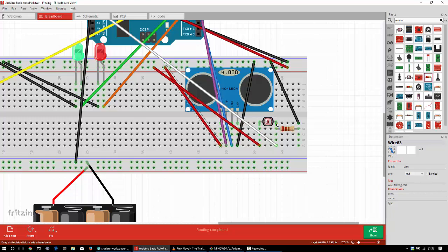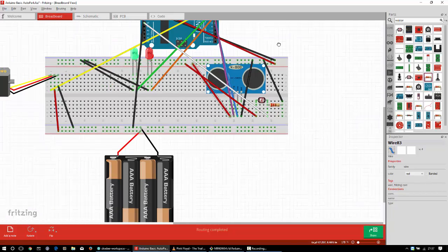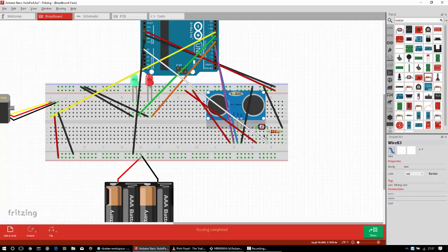In this example, on the right leg you put one resistor, and at the other leg of the resistor you connect the ground. On the other leg of the LDR you connect 5 volts, and on the first leg you connect to the pin as well. So that's analog 0. That's how you connect the LDR.